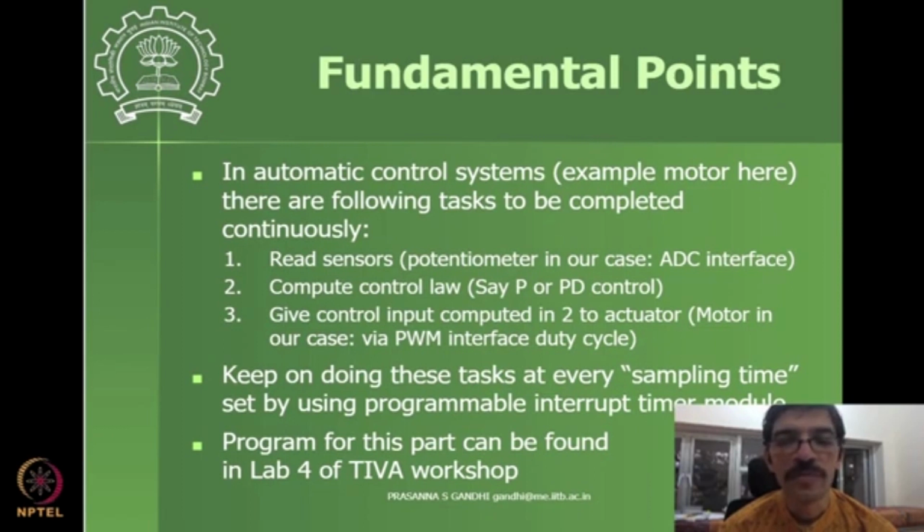The microcontroller is doing some task, and on some pin some signal comes, like a pulse, and this is an interrupt pin specifically designed for that purpose. When this pulse comes on the interrupt pin, the microcontroller will halt the current task for a moment and serve some other task which is defined for that particular pin.